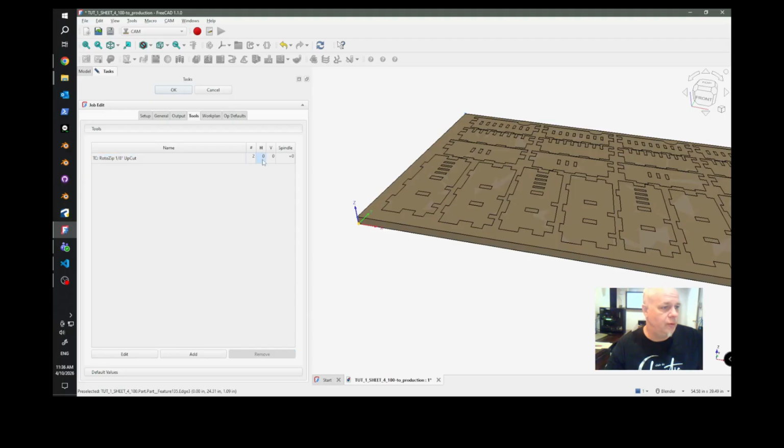And then I'm going to go to my horizontal speed. My machine can travel at 780 inches per minute, which is extreme for a lot of machines. If you don't have a production machine, don't even try to go there. But the horizontal cutting speed that I want to stick to is 400 inches per minute. The vertical travel speed that I want to stick to is 30 inches per minute. That's how fast Z goes down. And then 18,000 RPM on the spindle.